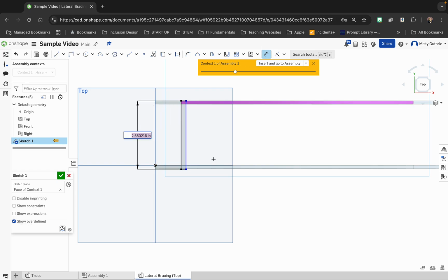So we're going to make a stick. The distance across, if you did 2.5, like I did, is 2.5 plus that additional 1/8 to go all the way across. Whatever distance you did your 2 side trusses apart, put that in, and then you can do plus 1/8 for your balsa stick. If you know the fractions, again, 1/8 is 0.125.